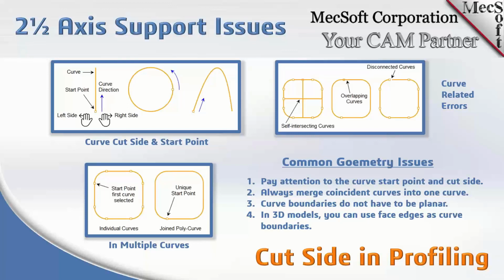So just be aware: if you go through the procedure of merging your curve geometry and understanding that it is merged, it is one curve, and you know where the start point is, all of these issues that you see in this dialog will go away. You resolve those up front before you start the programming process and have to run into errors. And again, here is a list of the common geometry issues that we just covered. Pay attention to the curve start point and the cut side. We stressed that a number of times on this slide.